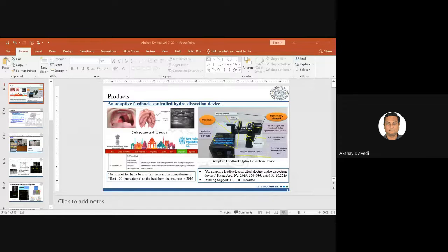So, here I have my first process, which was the original process on which we worked, and this process is named grinding assisted electrochemical discharge machining. The idea is that you need a process which can work on conductive as well as non-conductive materials. And you need a process that can create micro features, so micro domain machining is something which is required.